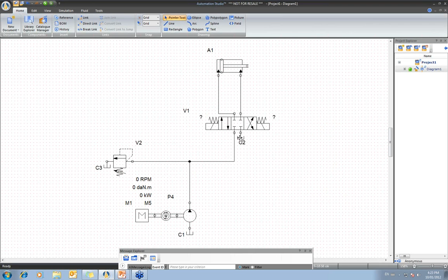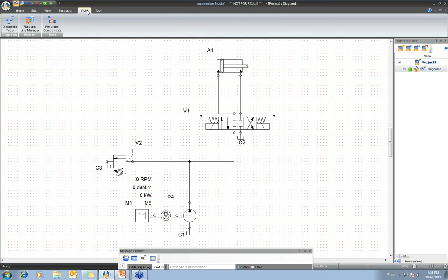So let's say if I wanted to show you that with version 6, we have also introduced some diagnostic tools in Fluid. So even if you have double lines like this, free connectors, or invisible components, etc., it will all be pointed out. Okay, so something that we were not offering before.